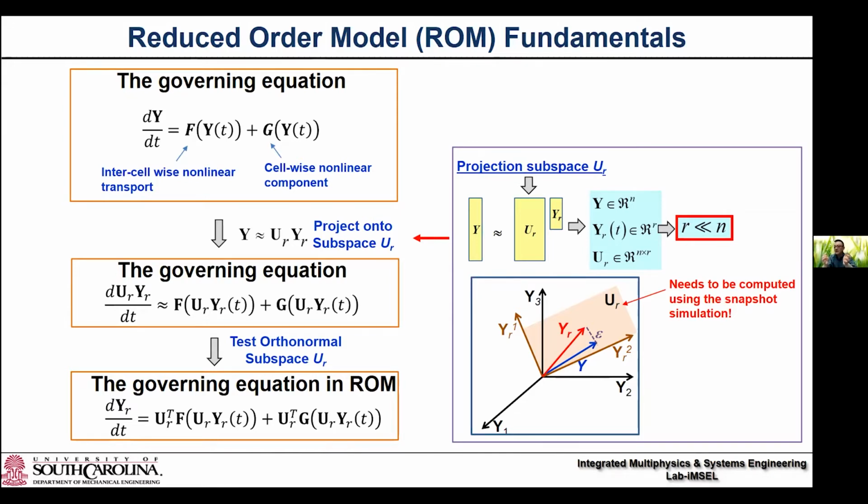When we talk about the heat flux, typically we need to calculate the gradient between my current location and my neighbor, the temperature solution at the neighboring cell, because this is a gradient. So we call it intercell. The reason I call it a cell is that in the finite volume method, the discretized control volume is a cell. In other words, this term will involve at least two cells, depending on the order of discretization.